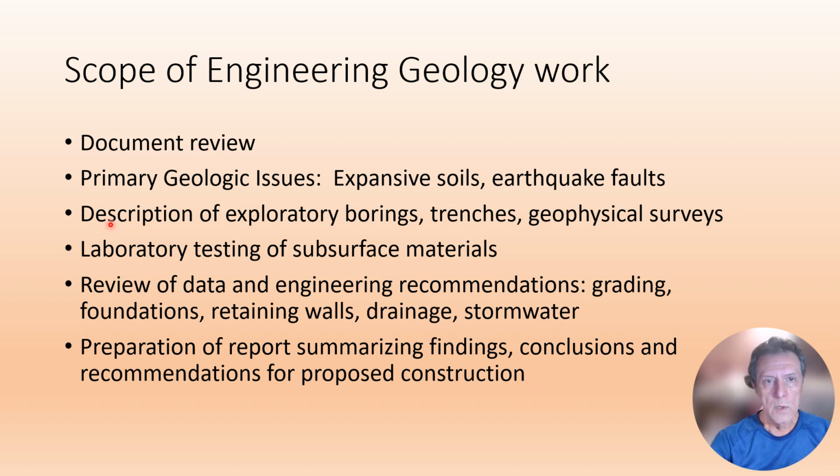You want to include a description of the exploratory borings within the scope of the engineering geology work, trenches, the geophysical surveys. Include data on laboratory testing of the materials. And in your report, you want to be able to review the data and engineering recommendations for site-specific recommendations, including grading, foundations, retaining walls, drainage, how to handle stormwater.